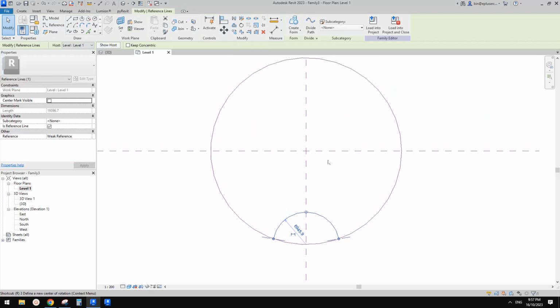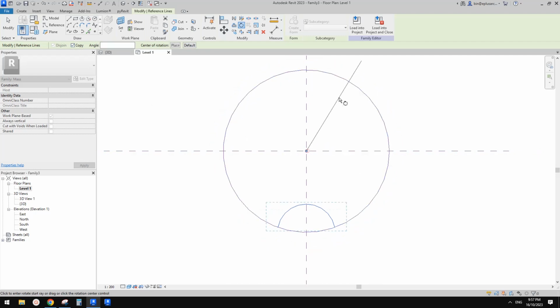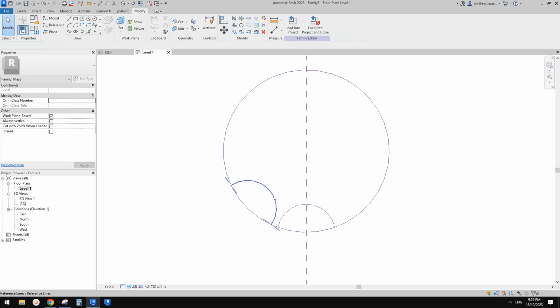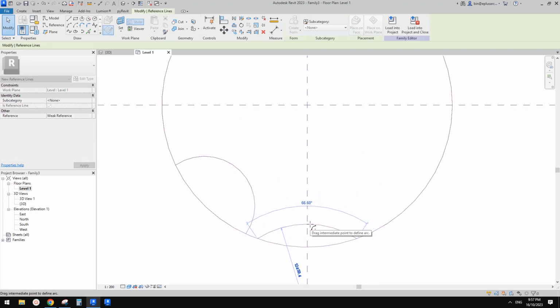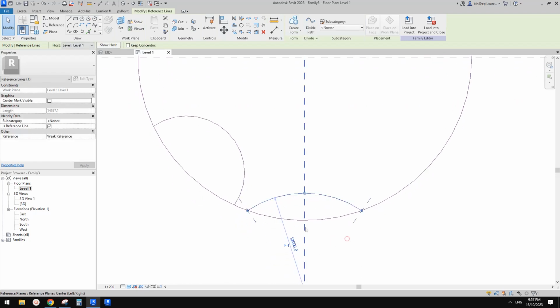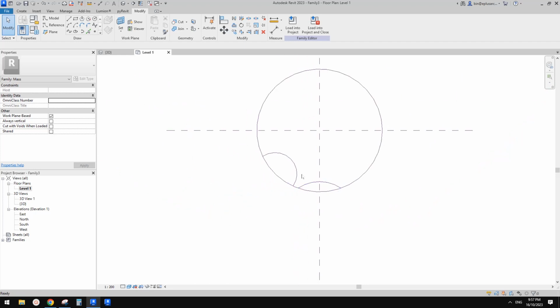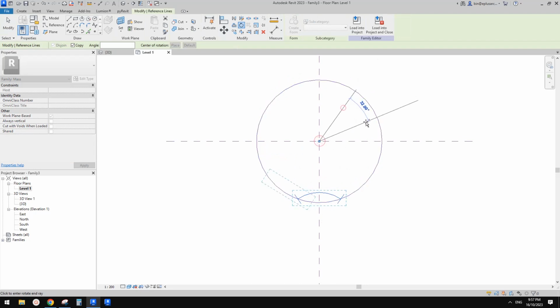Now I'm going to use RO, rotate, space, copy. Copy checked, and rotate 8, so it will be 360 divided by 8. Okay, it looks like it's too big. So maybe I'll type in 12 meter. I think that looks okay. And then I'll delete this. Again, rotate, space, and equals 360 divided by 8.